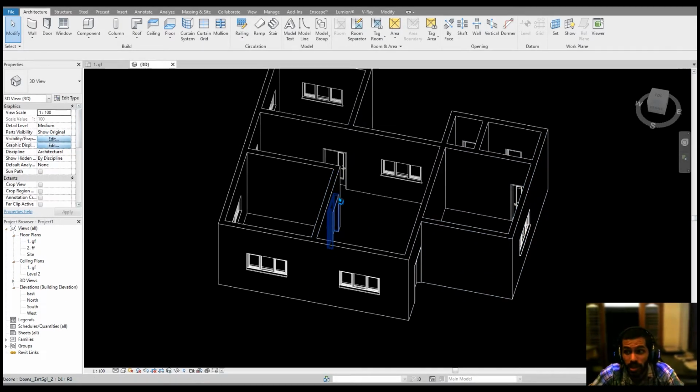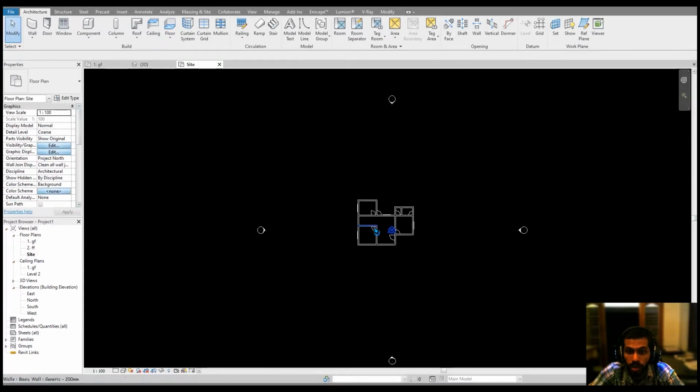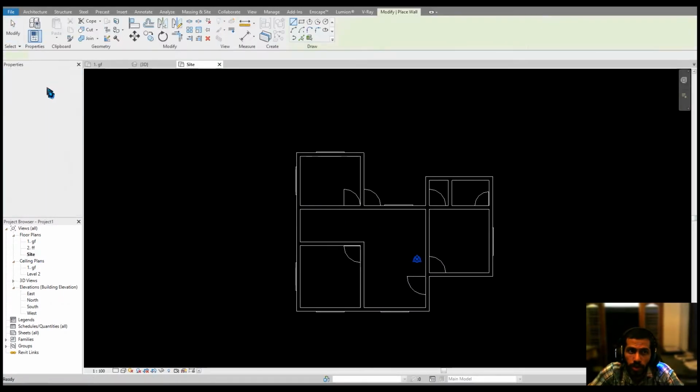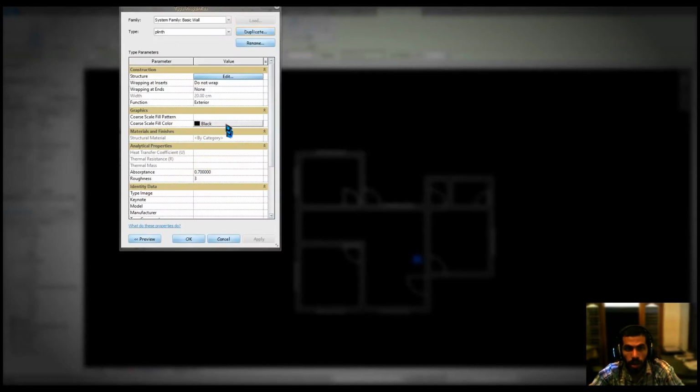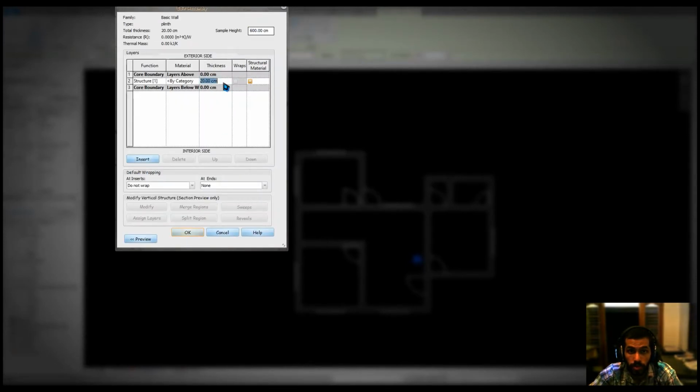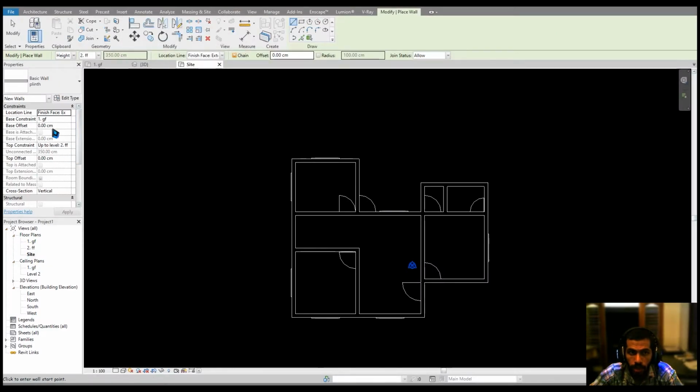So in order to place a floor and plinth, first I like to place the plinth, so I'm gonna get into site, and I like to create a new wall, so maybe duplicating that and renaming it as plinth. And as you go, the size will be like maybe 10 centimeter. And I can change the material, but I'm not really interested in rendering. And the height will go right from -45 to level 1 or to the ground floor.